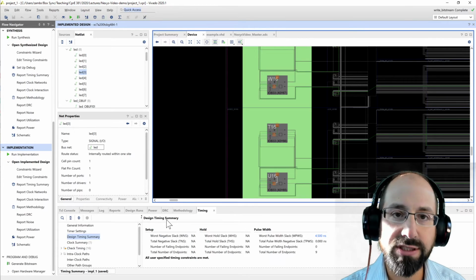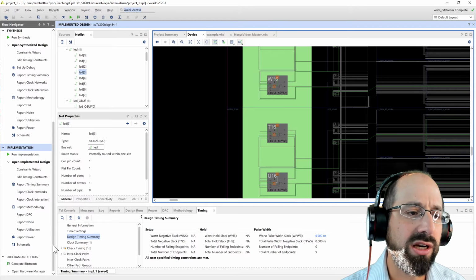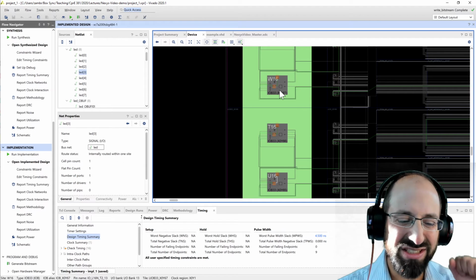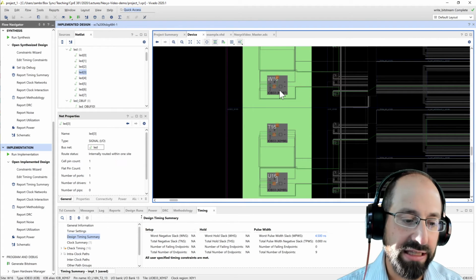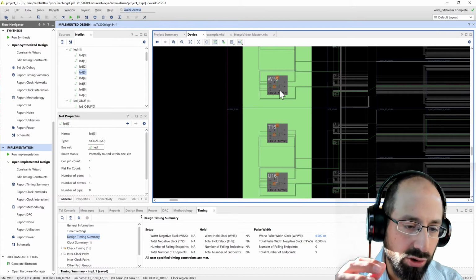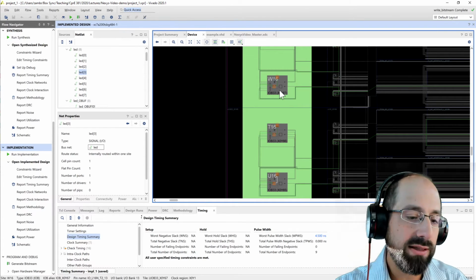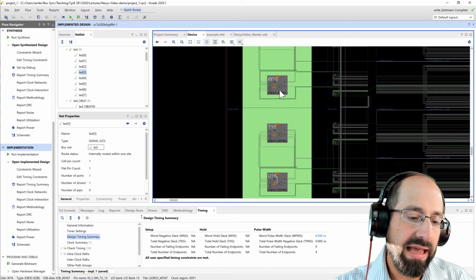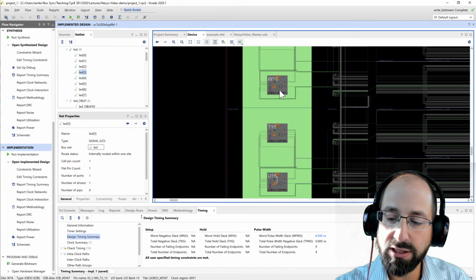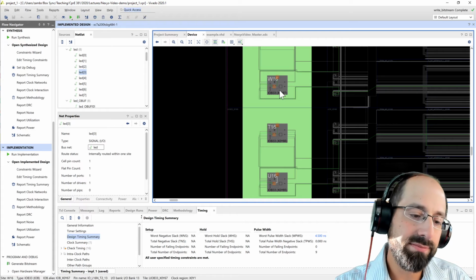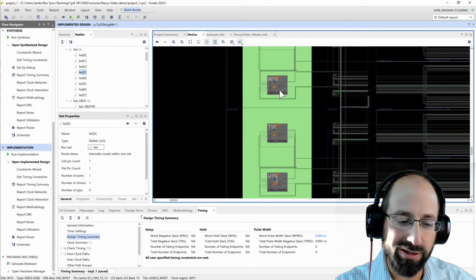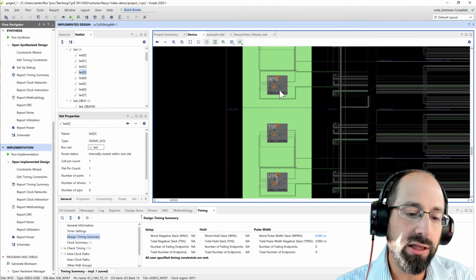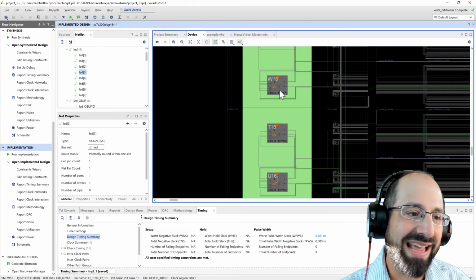So generating the bit file should never take all that long because it's a one-to-one correlation of this representation of what's happening on the underlying FPGA and just the ones and zeros to be actually loaded onto the FPGA. I mentioned those lookup tables. That's the core element that we have here, just memories. In this case, on this device, there's 64-bit memories, and they're used to store the truth tables. And so that programming process for your FPGA is really just a big memory write of various locations. It's got a little bit more complexity than that, but it's basically just updating a really large memory. Because that's what your FPGA ultimately is, a really large distributed memory. And that's what that process would be doing.